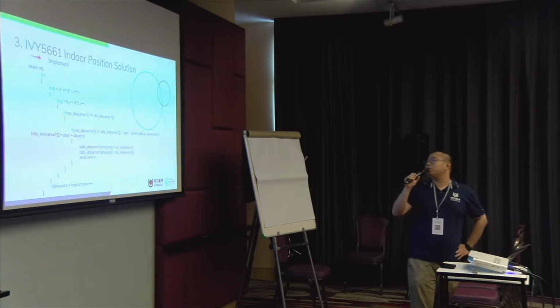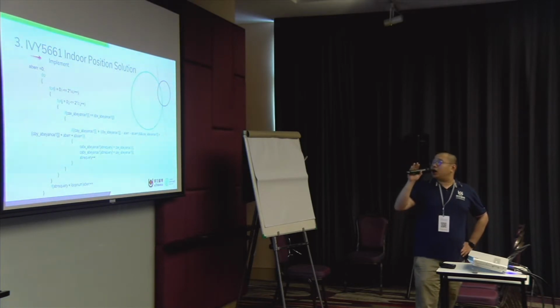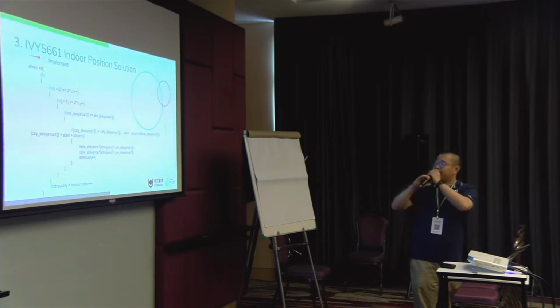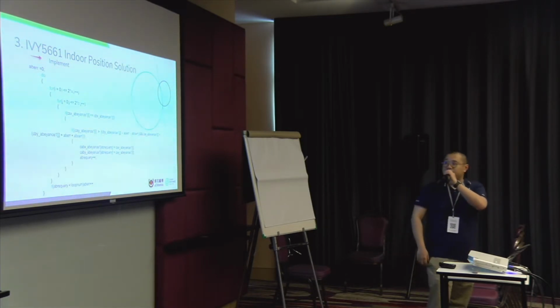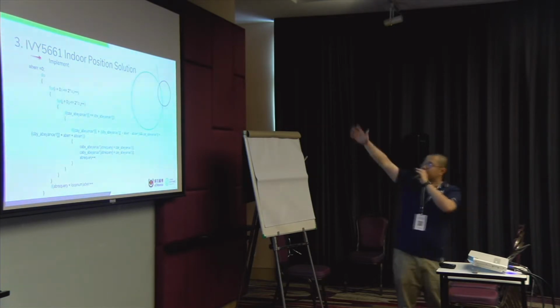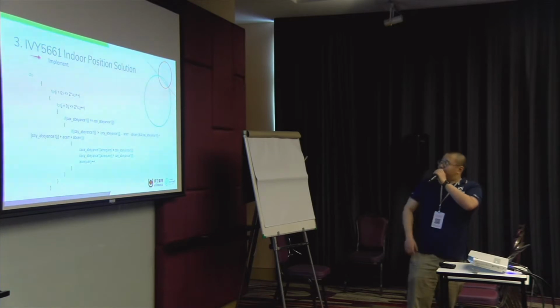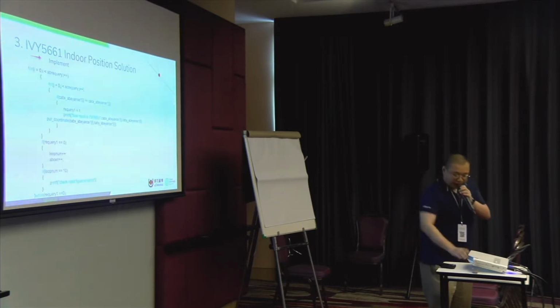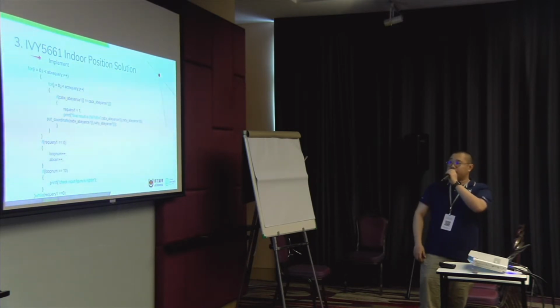Here is the code showing how we can use this function. First, we need to calculate the coincidence points of 2 circles, and a line, and the station will be on this line. And next we calculate another 2 circles, and the station will be on another line, and with 2 lines, there will be only 1 coincidence point, that's the coordinate of the station.